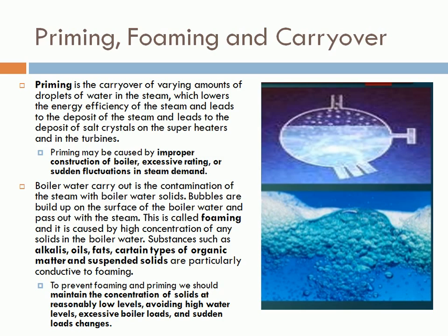Sensible locomotive management by the operator will help to prevent the occurrence. The phenomenon is particularly evident in areas of impure water, where boiled water creates a foam or a mist of droplets filling the space that collects steam at the top of the boiler, and is drawn down the steam collector pipe in the form of sludge water. And if boiler water is condensed and reused, then any oil or grease must be extracted, as such contamination is particularly likely to give trouble, right?